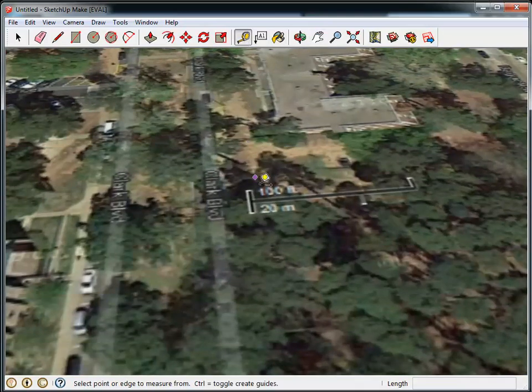And use the tape measure tool to rescale this image so that it's not just a couple of feet wide, it's actually going to be 100 feet. So I clicked at the beginning and end of that scale. I'm typing in 100 feet on the keyboard. You can see that down here in the lower right hand side. 100 single quote like that. Hit enter. And it didn't look like it took there, so let me try again. Click here and there. 100 feet and then hit enter.